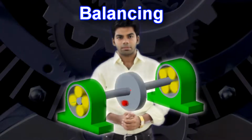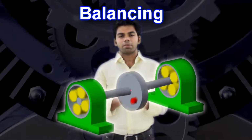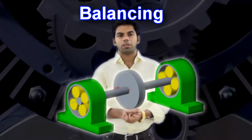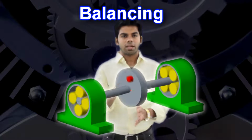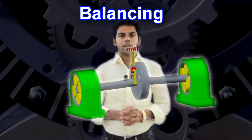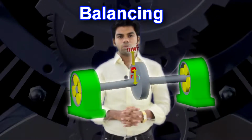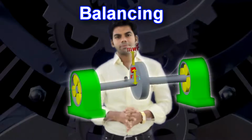Now suppose we have an unwanted mass here, a disturbing mass. What will happen? Because of this extra mass, the center of mass of the rotor and the axis of rotation will not coincide. Suppose that mass is at a distance r. This mass will produce a centrifugal force m omega square r, which is directed outward, obviously.